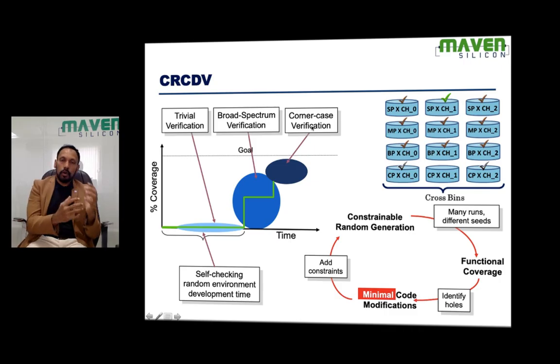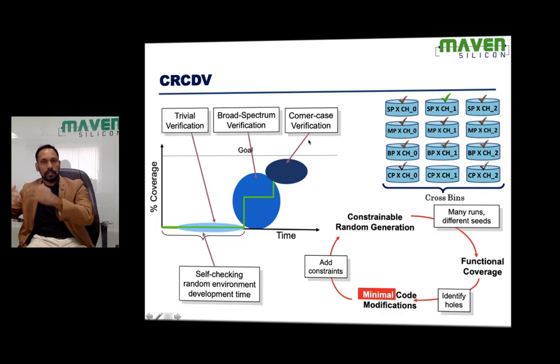Instead of generating only small packet, big packet and corrupt packet, can we try the combination? Maybe 100 small packets, 10 big packets and 1 corrupt packet. If we send the sequence to the router and see how the router is going to behave, that's called corner case verification. That's how we can define new test cases and improve the coverage further.